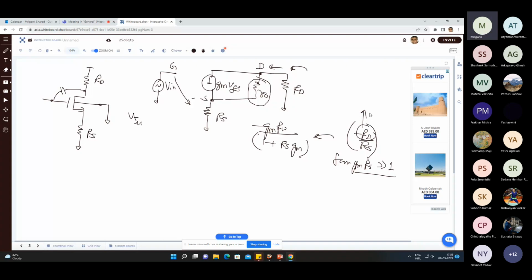In your basic physics, you understand that if you increase the temperature, your scattering increases, as a result of which the electrons face more resistance as they travel through a resistor, and therefore the resistance will go up. The resistivity of the material will go up as the temperature increases. So in general, they will have a positive temperature coefficient. But the ratio of two resistors, to first order, remains fairly stable. It remains fairly constant.